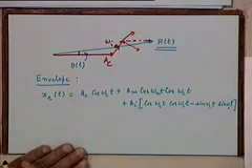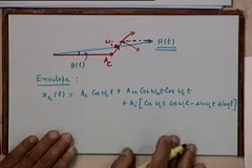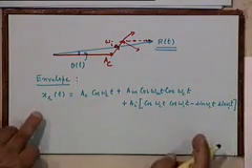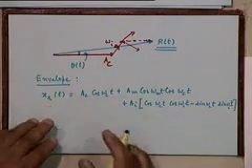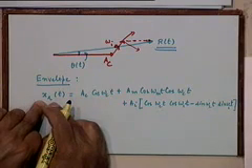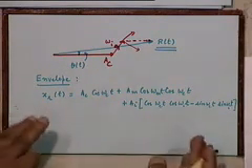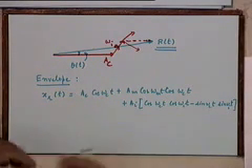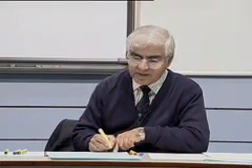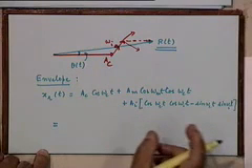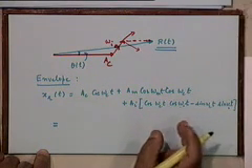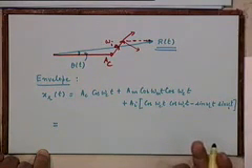And you know why I did this? What's the motivation for writing like this? Because I like to express this received signal in the quadrature representation. Any narrow band signal we know we can write in quadrature form, right? There is an in phase part which is multiplied with cosine omega CT, and there is a quadrature phase part which is multiplied with sine omega CT.